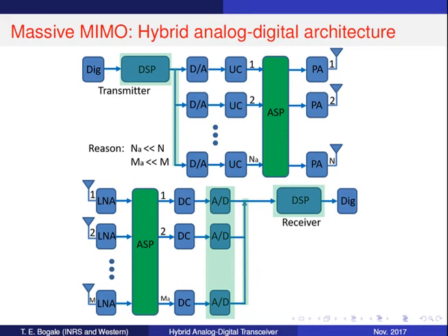In general, one can design or program the ASP unit to achieve different objectives, such as to maximize the SINR at the input of the ADC unit, to maximize the average SINR of all ADC units, and so on. In all cases, the main jobs of the ASP units are to modify and combine the incoming signals according to the desired phase shift and amplitude levels.